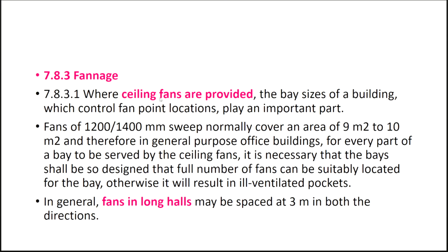Again, with respect to the ceiling fan, in case a ceiling fan is provided, what area will it normally cover? What it says is that fans of 1200 millimeter or 1400 millimeter sweep, meaning the blades, normally cover an area of 9 square meters to 10 square meters. Therefore, in general, for office buildings, for every part of the bay to be served by ceiling fans, it is necessary that the bay shall be so designed that the full number of fans can be suitably located. Otherwise, it will create ill-ventilated pockets.